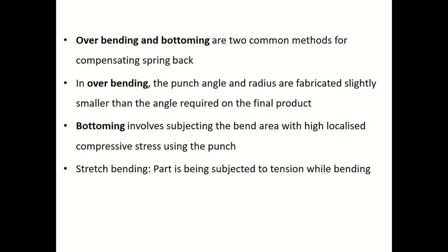So this also ensures that after bending the part acquires the desired value. Which means we are using a punch to deform the bent region again. So that's called the bottoming.